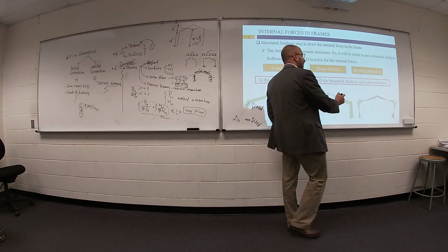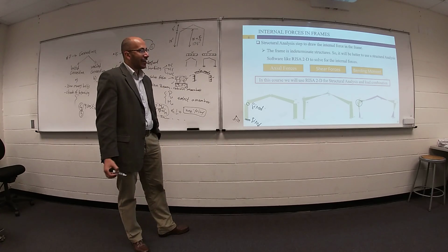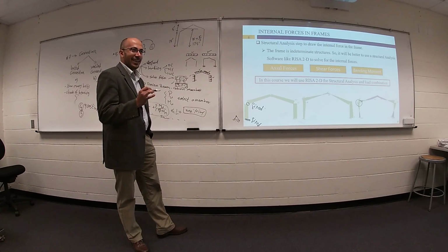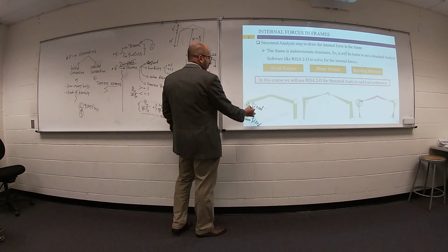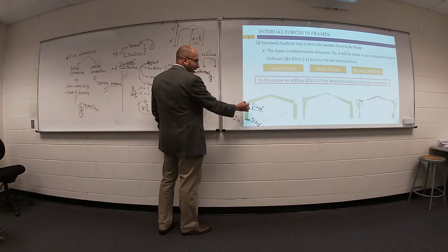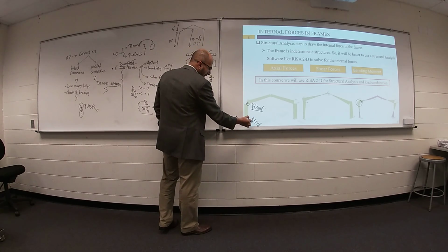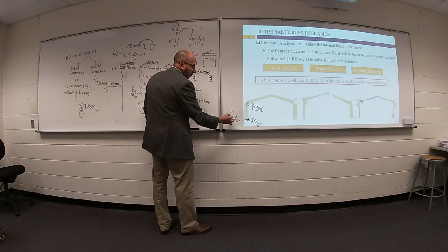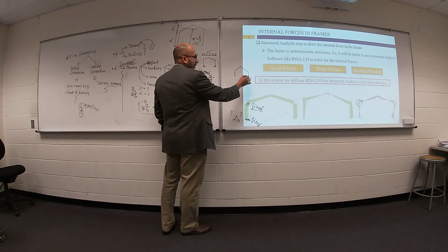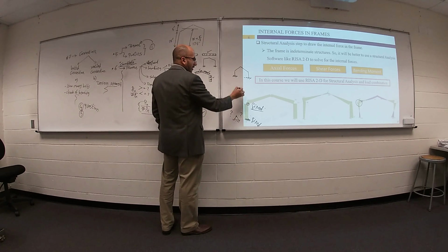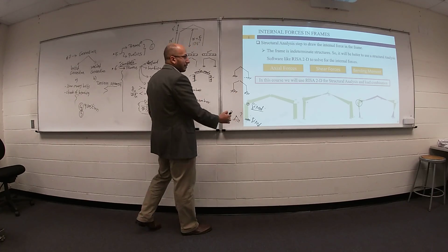For some reason, we have moment here, so I cannot assume it hinge. Also, I cannot assume it completely fixed. Something in between, but to make our calculation simpler, assume it fixed. So the end condition, assume it fixed. But for the second end, as you defined your frame, if your frame is fixed, define it fixed. If your frame is hinged, it will be hinged.